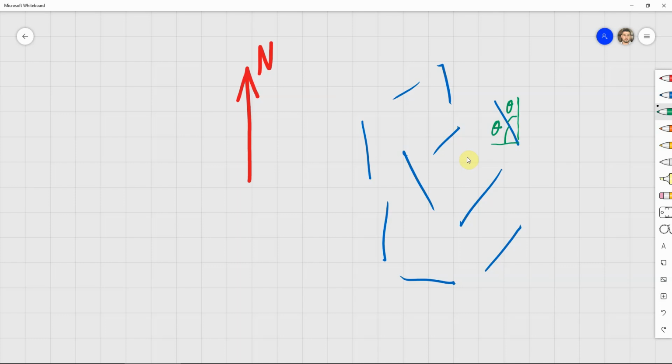Because we have our convention that we are starting from north, moving clockwise, that will give us a direction, not only an angle. So the angle has a specific direction, clockwise measurement. So when I'm saying an angle of 60 degrees, that means I'm starting from a point and moving at 60 degrees from our imaginary line, at that starting point, the imaginary line representing north, and I'm measuring from that line 60 degrees clockwise.